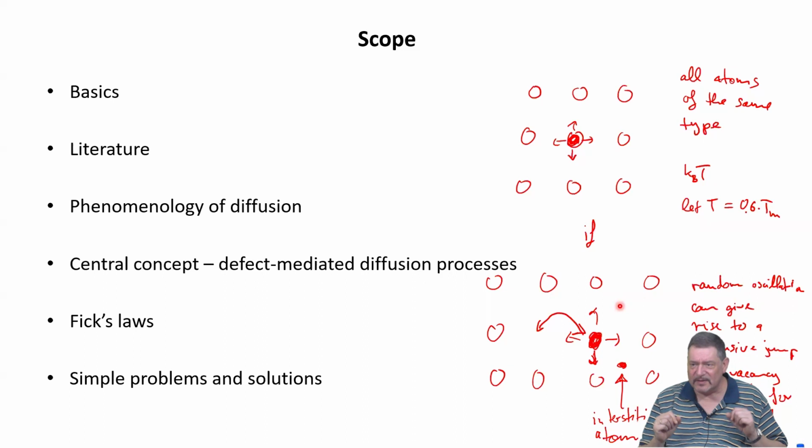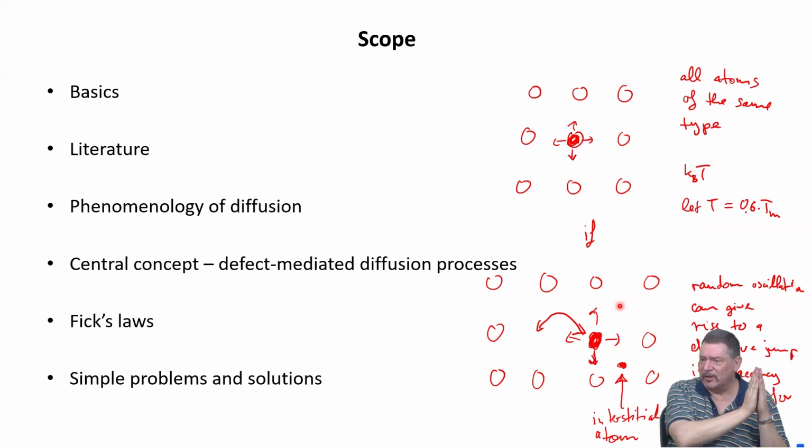The trick is to use a radioisotope. So the same element, let's say gold, but having a different number of neutrons in the core of each atom. We apply this gold tracer and let it diffuse. Then we can section the material and count, I will show you how, the number of radioactively marked atoms in each section depth.